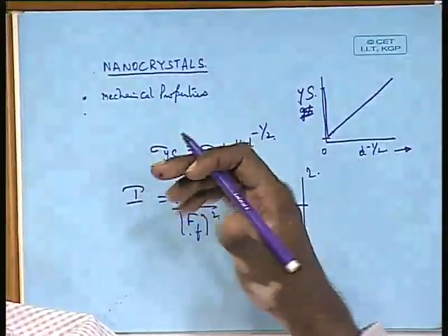You may also ask me, what about the creep resistance in such a nanomaterial? We will talk about it when we talk about grain coarsening in these materials and how to control the creep in such materials, because we know that if you have a fine grained material, the material easily creeps. So at high temperature in principle you should lose the strength, but in some of these materials even the high temperature strength, as I showed you in the previous case, is much higher. How are you able to achieve such high temperature strength without any creep occurring?